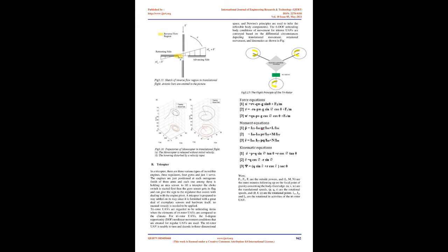Engines are set at the tip of the flight bars and payloads are arranged on the flying bars, so the center of mass for the total aircraft may be made inside the space between the flying bars. Engines apply force to rotate the aircraft, then the rotating mono-wing gives lift force to the aircraft. During a standard flight, the monocopter turns around the center of mass.